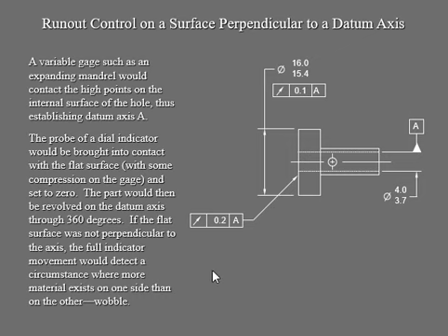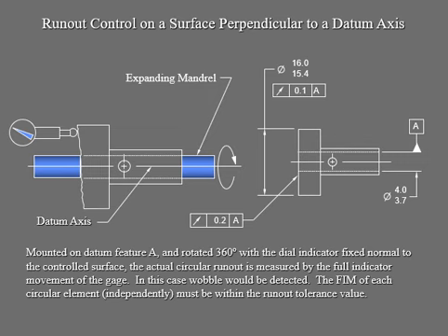Wobbling means the material of that part is going to be more on one side than the other. You can see it when you measure it. You will see the measurement numbers increase and decrease up and down from that 0 point. So now we can see that.